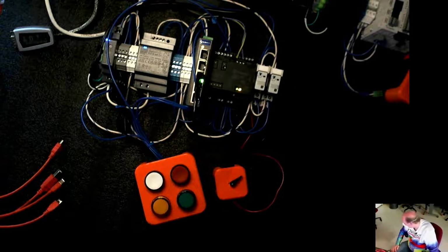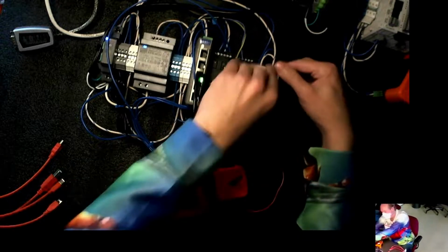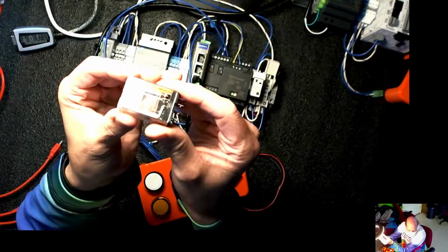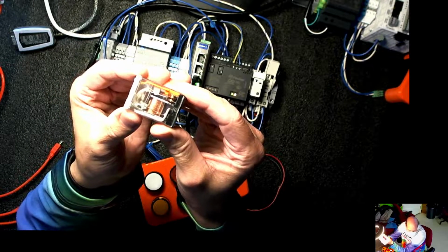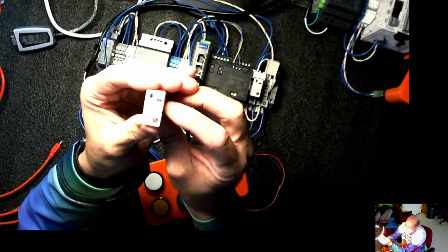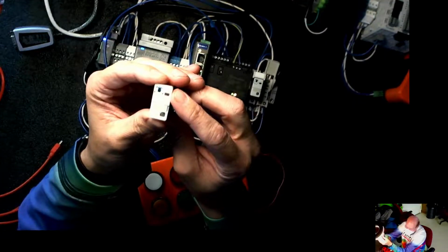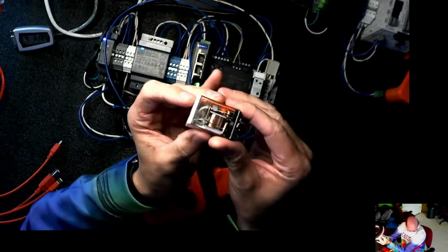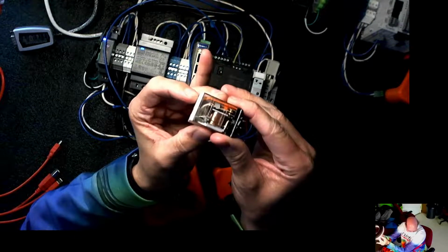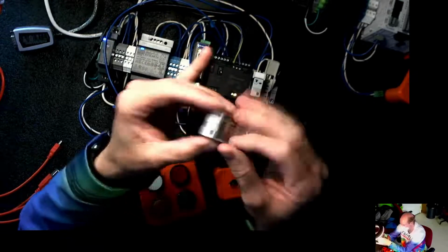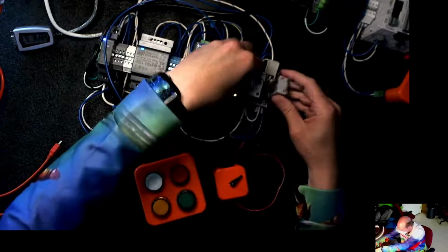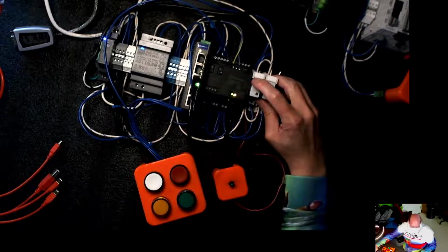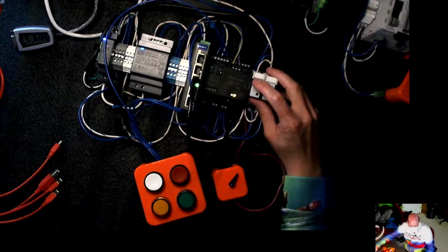These relays are actually pretty cool. Now let's pull one out and show you. They got a little window so you can see inside, and that little orange bar you can see through the small window here. And then there's a little green button that you can use to actuate the relay that actually moves the contacts mechanically and not electrically. And then this goes into a plug socket. And so I can actuate the relays manually, which might be familiar to you if you've worked with air solenoids also.